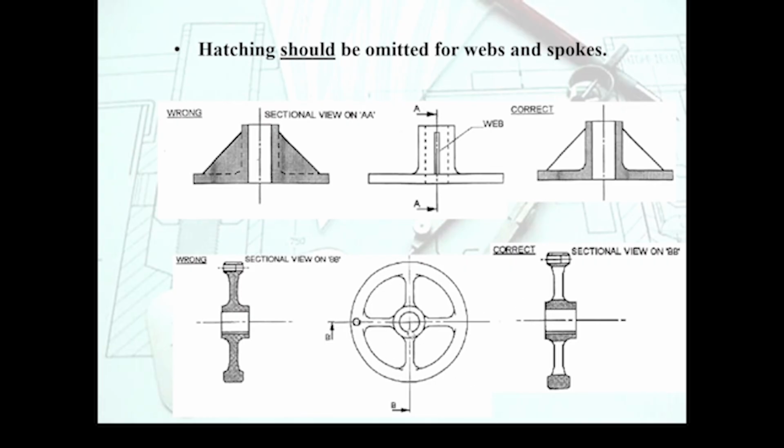The way we produce this is, if you are looking at this object from the left hand side here, whatever we see below that level, we draw that there, and then the rest of the view is rotated above there, and we draw that as if it is literally stretched out up to this point, which is accompanied by the label that says sectional view at BB. Once again,